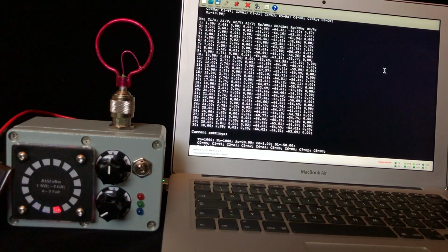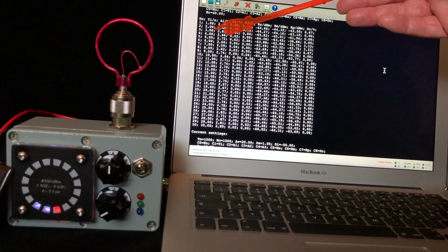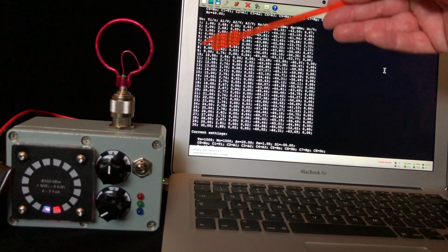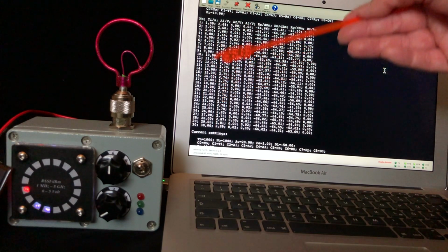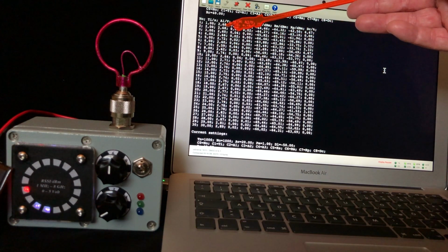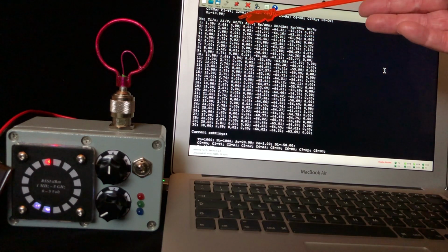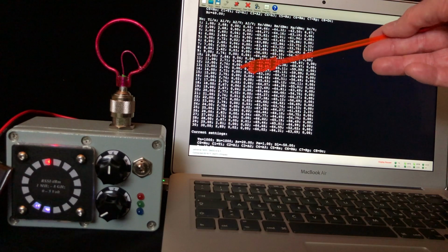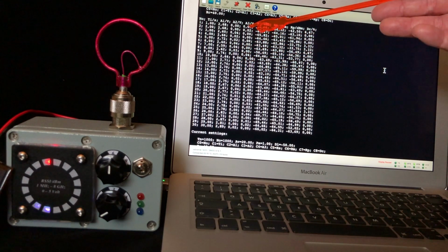Now let's have a look at the data that we get in the text mode. As a standard, we get a running number in the first column. Then we get a timestamp in seconds. Then we get the voltage on input A1, where we currently connected a solar panel. In the low light, it is giving us only about 2.7 volts. Then we see the voltage on the inputs A2 and A3.